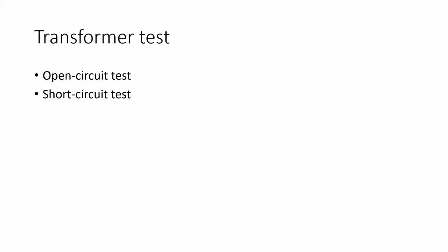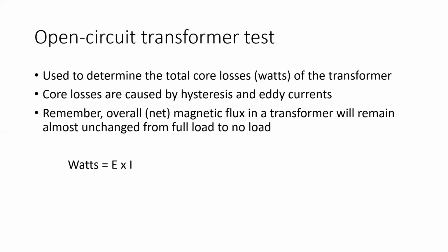Transformer tests. Transformer tests typically are two different categories: open circuit test and short circuit test. Let's see what the difference is between them and what they're going to tell us. Open circuit tests are used to determine the total core losses of the transformer.